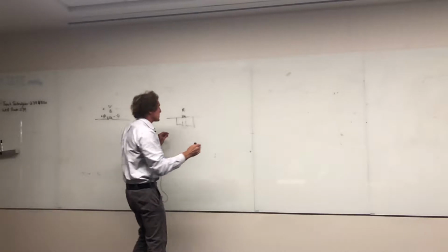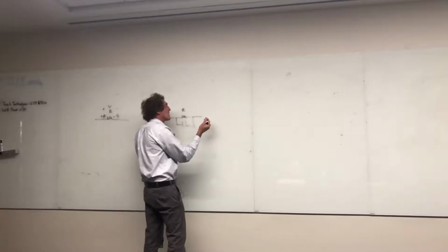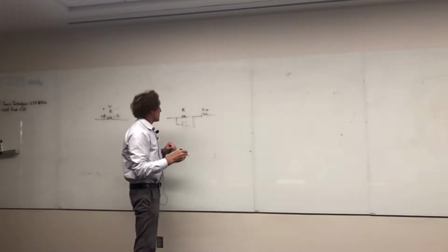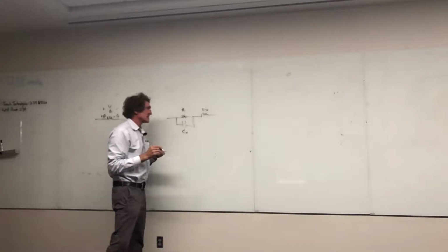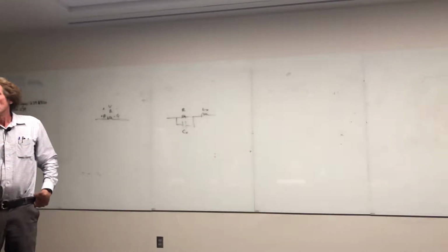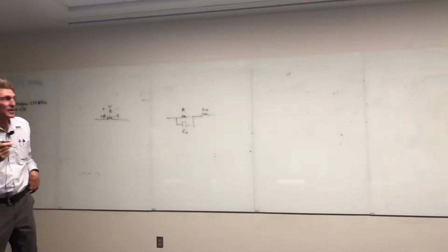There's also the inductance. The wire has inductance, so there's an LX associated with this, and both the C, I call it CX. Anytime you see an X, it means you wish it wasn't there. To me, that's the way I look at this. These are things that are parasitic: parasitic capacitances, parasitic inductances. You wish they weren't there, but they are.